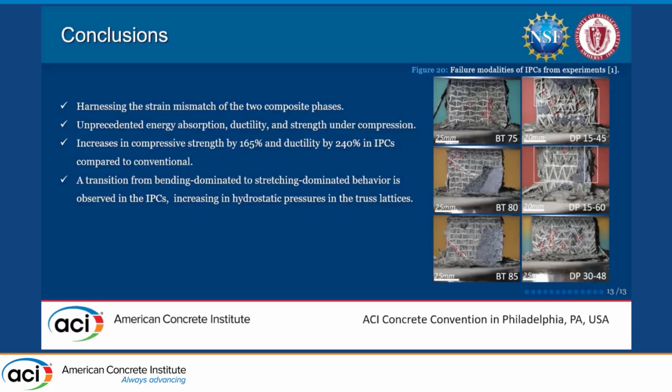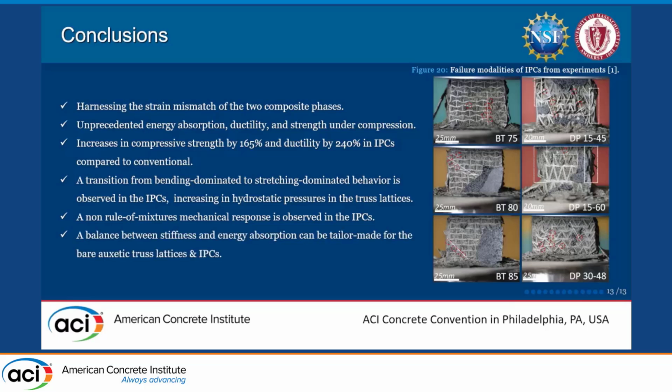We have also observed the transition from the bending-dominated behavior of the truss lattice phases alone to stretching-dominated behavior inside the IPCs, which also leads to an increase in the hydrostatic pressure of the truss lattice, and that essentially let us squeeze every last drop of strength that the lattice can give to the IPC. We also observed a non-rule of mixtures mechanical response inside the IPCs, which was quite interesting in this case.